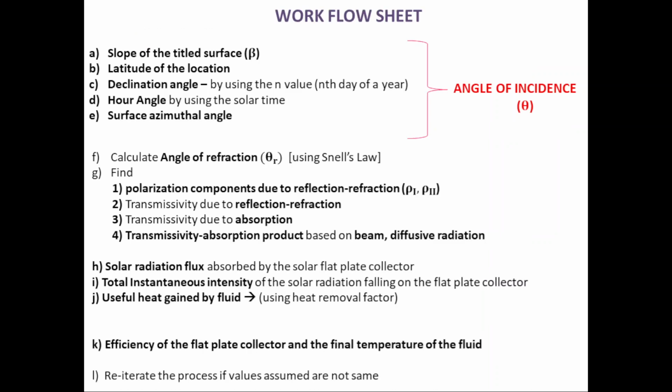So if you see, this is a workflow sheet. This will be useful for calculating the efficiency of the flat plate collector, the detailed step by step process on how to calculate the efficiency of your flat plate collector or your concentrating solar collector and the final temperature of the fluid that is coming out of your flow tubes.